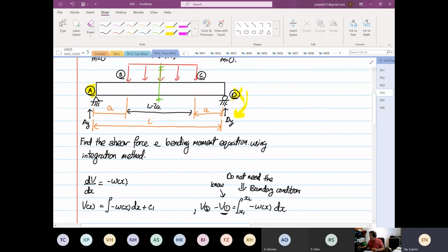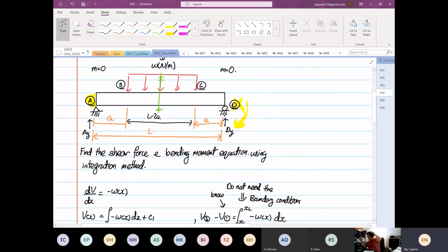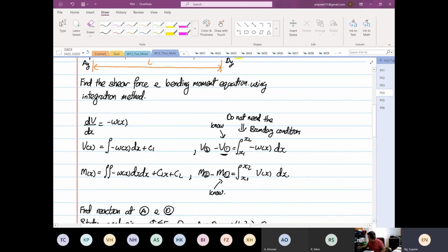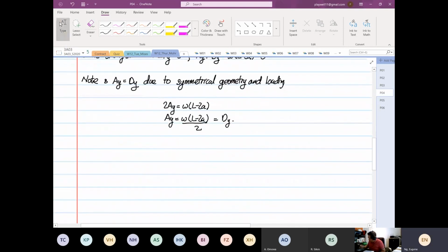So we're going to develop what we call piecewise equation. We're going to look at these points that we actually need. So we're going to divide into sections. Okay, so we have point A. So we divide the section based on the loads. If there's a new load, we have to divide it, or support. So point A, this is because we have our reaction at A. Then we have to do between point A to point B.